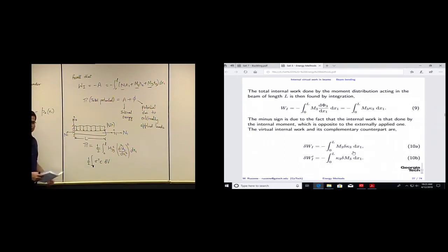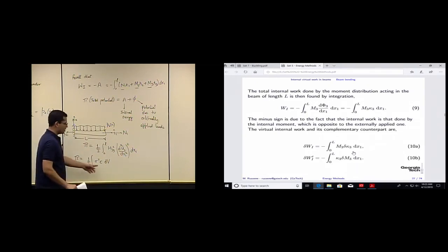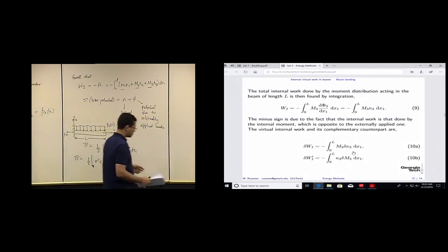So that's what the total potential equals, and it also equals that. You can also get it by doing that. So you have to use constitutive equation, sigma is equal to E epsilon or nonlinear constitutive, and then you have to use strain displacement relation, right, which we have derived for Euler-Bernoulli beam theory, and then you get this expression.